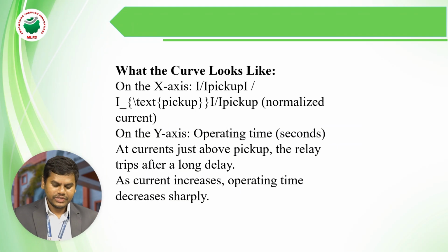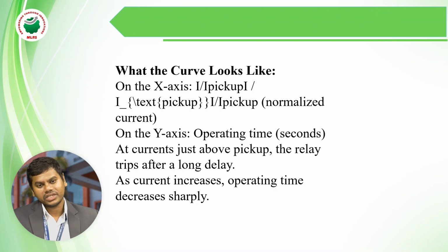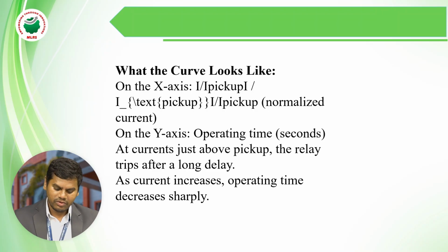Next, what do the curves look like? On the x-axis it represents the normalized current, the measured current, and the y-axis represents the operating time, time in seconds. At currents just above the pickup, the relay trips after a long delay.